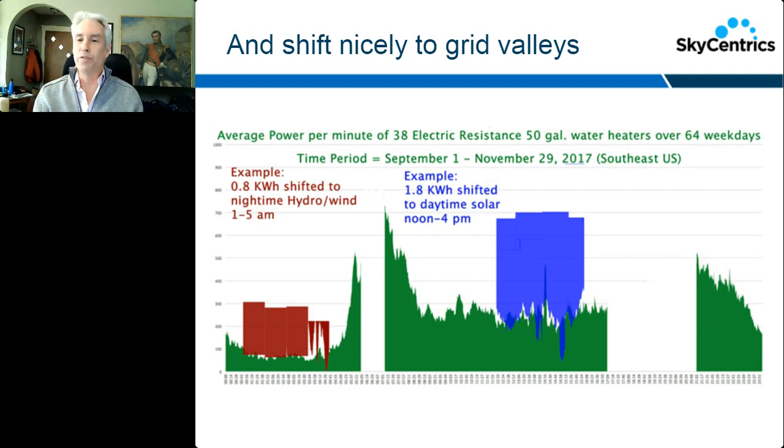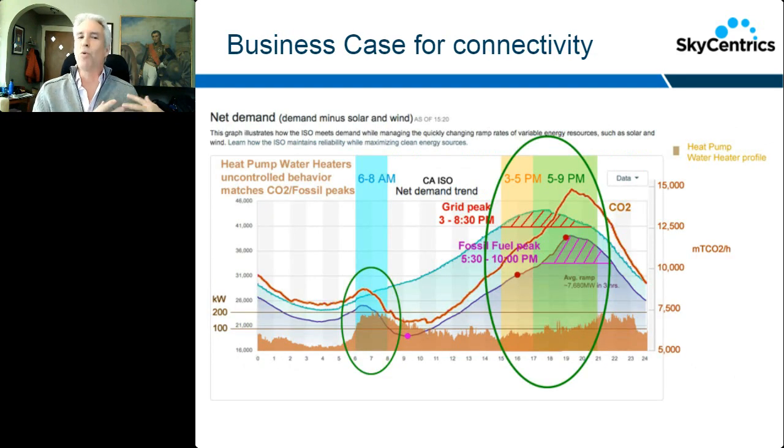Now this is the time of use value that NRDC delivered and convinced the California Energy Commission to say, hey, see this time of use, we can shift when we shift water heater. But I'm now going to show you why I think it's critical to have more than time of use as quickly as possible. So here is the heat pump equivalent of the graph. Now, instead of 700 watt hours of the electric resistance, you're seeing a watt hour that's more close to 200 watt hours, this kilowatts right here. Well, no, sorry, that should be watts. And then a little bit less of an evening peak. And I'll show you some data that was presented last year where it's a little higher than that, maybe up to 300 watt hours.